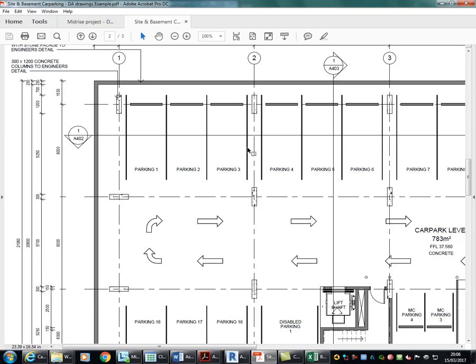So anything up to 10 metres, even 11 is achievable, but 10 metres is a good limit to put on yourselves. Then the beams don't need to be too big, or you can sometimes do it with just a slab without any thickening for the beams, which is really nice when you can just do a single thickness. But 10 metres will probably need some slab thickening or some beams, and that's easily achievable.